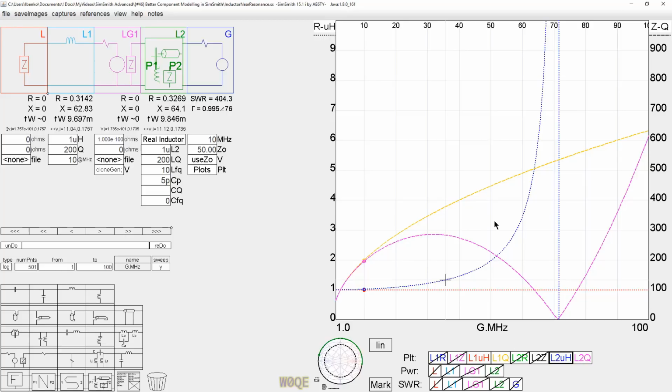So what we get here, and I've heard people say things. When I was a kid, I read an article one time where this guy was touting how this worked, and I had no idea how you could ever increase inductance by adding a capacitor in parallel with it. He was making a comment that this was basically some kind of free lunch. He couldn't get an inductor of large enough value, so he nearly resonated it, used the circuit slightly below the resonant frequency, and he was able to get this higher inductance. Well, he was able to get a higher inductance, but it was a lossier component. And as pretty much everybody who's been around the block more than once or twice should know, free lunches generally are not quite what they're cracked up to be.